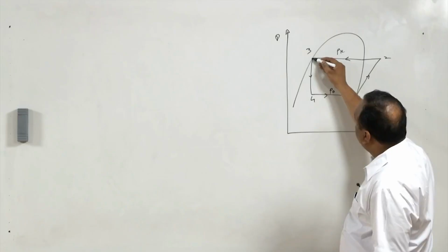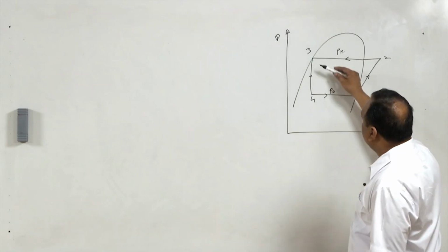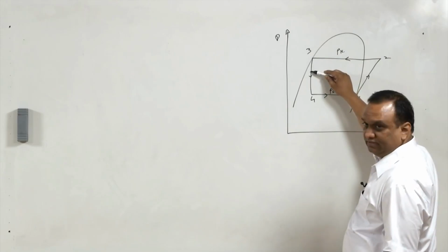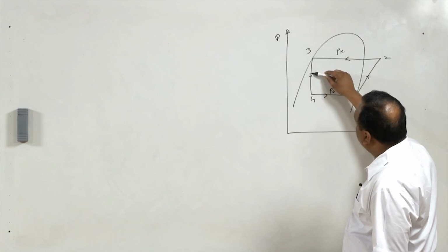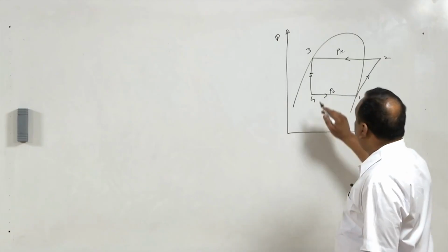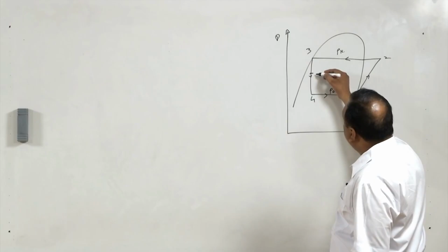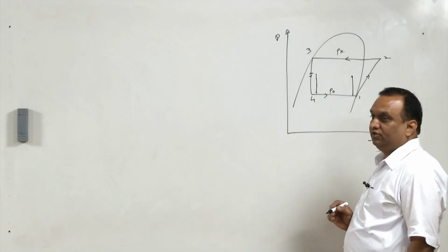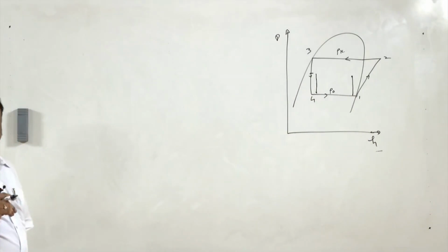Suppose it is a low capacity plant and capillary tubes are used as expansion devices. The refrigerant entering the capillary tube will be liquid, but slowly the flashing will take place. After expansion to a certain length, the amount of vapor becomes substantial. If we remove this vapor, because this vapor will get expanded and again be compressed, so in order to avoid this, a flash gas removal system is provided in the system.